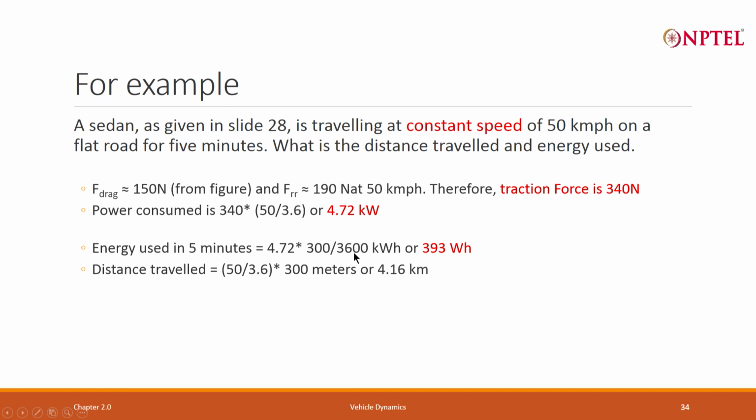I divide by 3600 to convert into hours, because I want to write it not in terms of watt second, but watt hour. If I do this calculation I get 393 watt hour. So, for 5 minutes I am consuming 393 watt hour. If I continue to drive for 60 minutes, I will consume 12 times this.